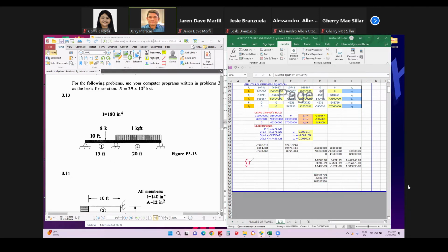You can compare this with the morning, the F, the K. This is our K, and this is our displacement. So what we will do is take the inverse, then pre-multiply F by the inverse of K, which gives the unit matrix. So the displacement matrix should be the inverse times the force matrix.